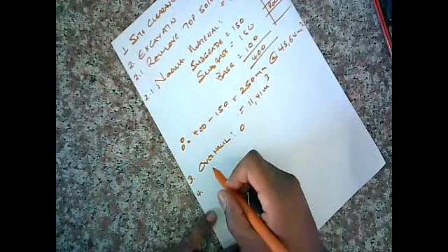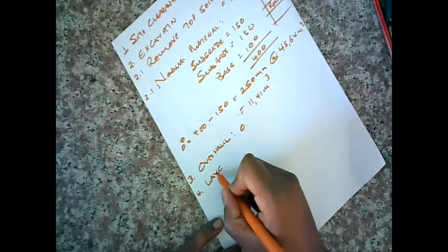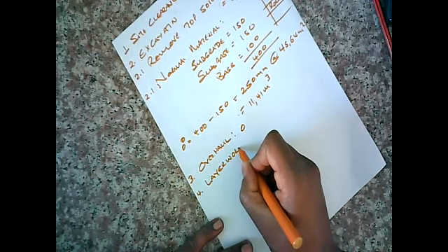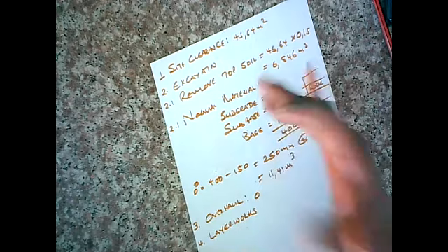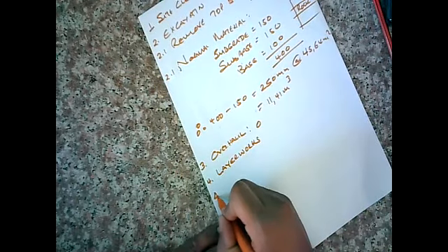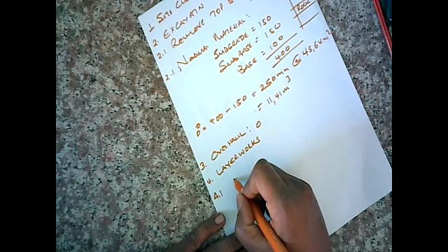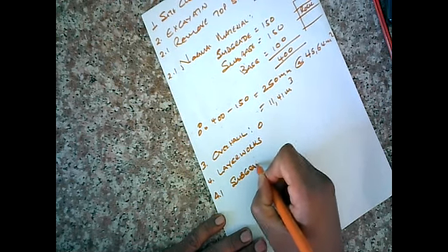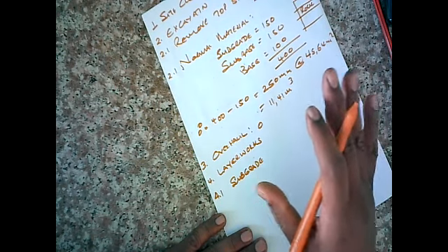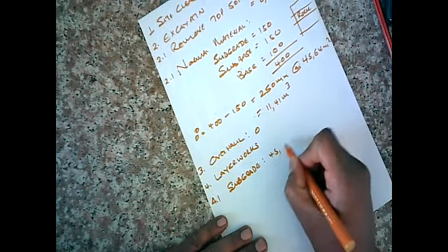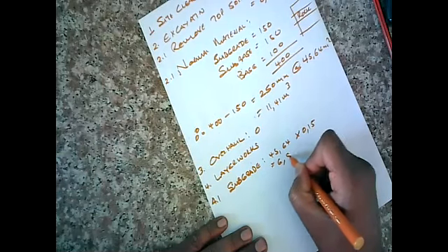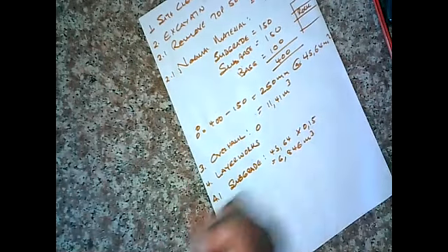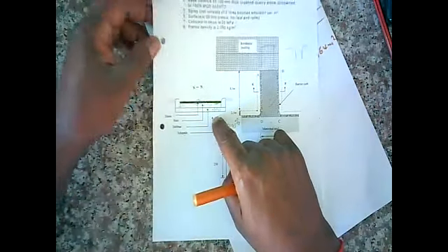All right. Now let's talk about this thing, layerworks, being the layers of the road or the pavement. All right, let's look at 4.1. Starting from the bottom, subgrade. You have to start from the bottom. We know the area where the subgrade lies, 0.15 is the depth. That's 6.846 meter cube. And let's go back to the sketch. All right, subgrade, here it is. All right, what's next? Subbase.